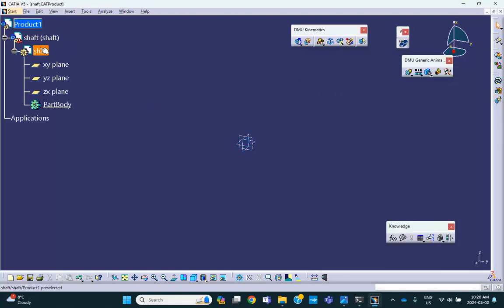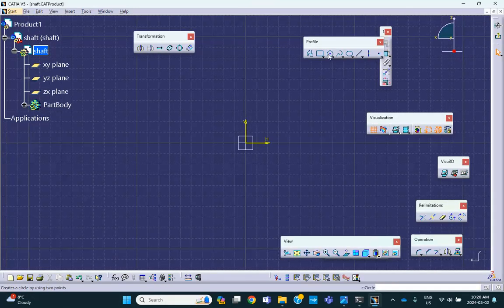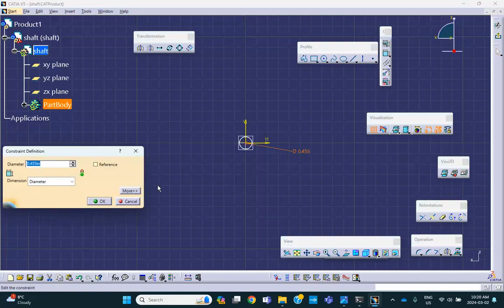So double click on a convenient plane. I'll make this vertical plane, which is the yz plane, as my starting location. So all it is a disk. Let me give some dimension here. Actually, just for me to have an idea what's going on here, let me dimension this thing to be something. It says this seems to be in inches, right? So I'll go with maybe 20 inches. Sorry, 20 millimeters. See how it looks like.